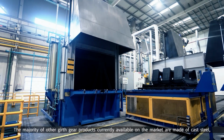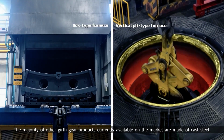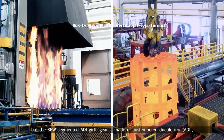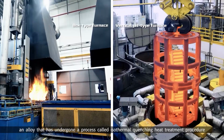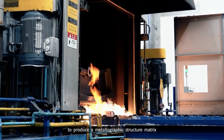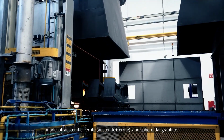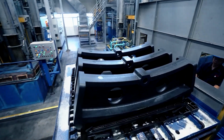The majority of other girth gear products currently available on the market are made of cast steel, but the SEW segmented ADI girth gear is made of Austemper ductile iron, ADI, an alloy that has undergone a process called isothermal quenching heat treatment procedure to produce a metallographic structure matrix made of austenitic ferrite, austenite plus ferrite, and spheroidal graphite.